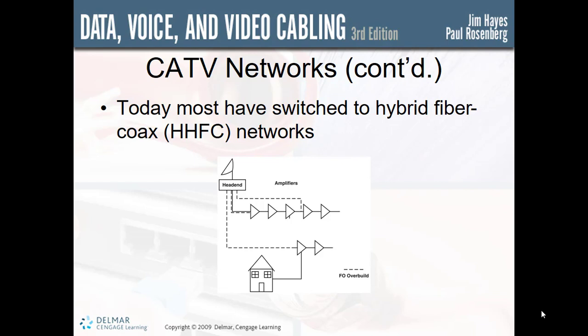Fiber is added to the CATV systems already in place by a fiber overbuild, where a fiber optic cable is lashed to aerial coax or pulled alongside in its ducts. Large systems use fiber to distribute signals to several towns because fiber has the capability of transmitting long distances, saving on the cost of additional head ends.